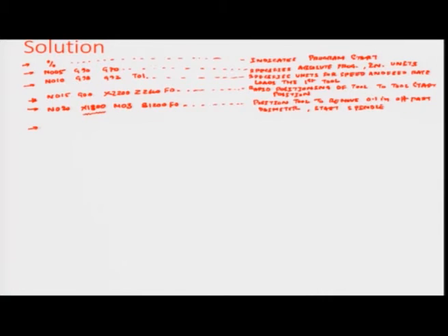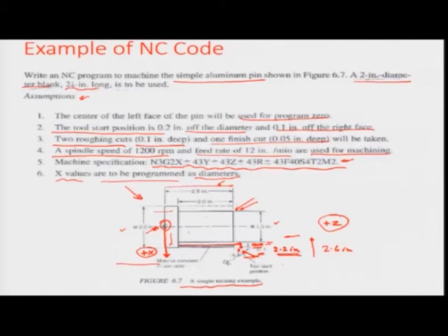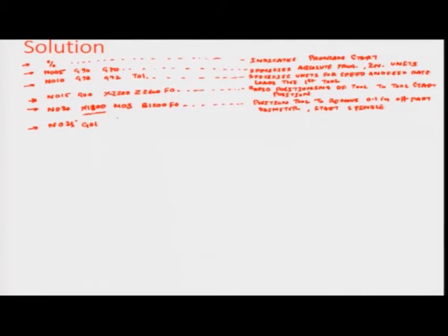In this particular case we will write this command as N025, the feed, a linear feed. So, we will change the G00 option to G01, and we have to go to a certain Z value. If you look at the Z value which it needs to go to, it corresponds to 0.5 inches, right about here, which is the size of the head of the pin as given in the diameter. So, I will say this corresponds to a position Z500 up to which the tool must go, and the tool must do so with the feed which is given to be 12.